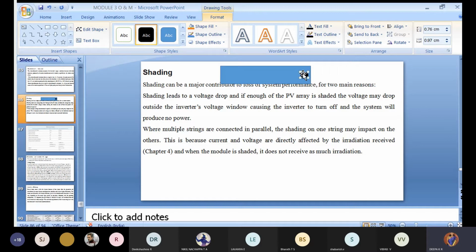Here, this is the only part where you're not having conversion, and losses are happening because this cell is not contributing anything, not converting anything. But due to the radiation on the rest of the area, huge heat will be concentrated on this particular cell, and it can damage the output of the module. Cell damage can happen, and if it persists for a longer time, it will affect your module output.